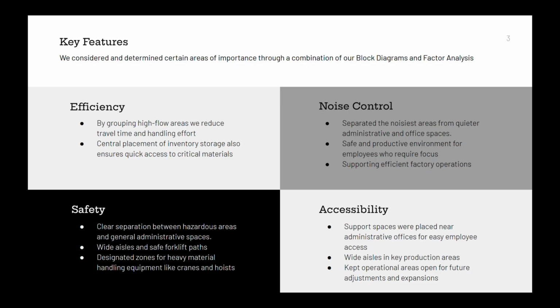For our key features, we used our block diagram and factor analysis to determine these and to make sure we emphasize them in our layout. For efficiency, we group the high flow areas to reduce travel time. We have a central inventory placement for quick access to materials.